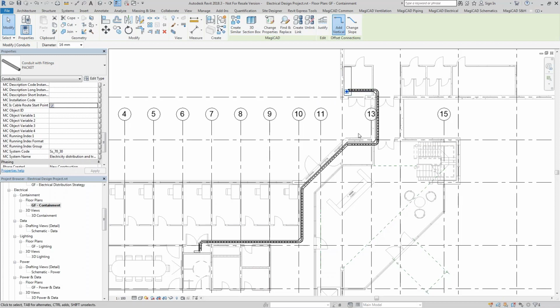So drawing this cable packet, what this allows us to do is connect multiple objects to the same circuit path, and then it will give us the overall distance, including any kind of working backwards like this here. I mean, the distance isn't going to be too different using an orthogonal line here, but because it does return on itself for one portion, it is going to be maybe a couple of meters different.